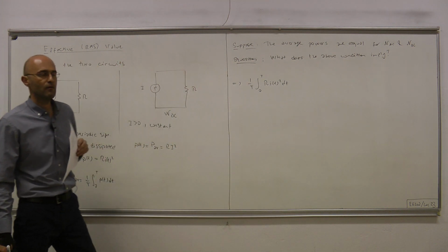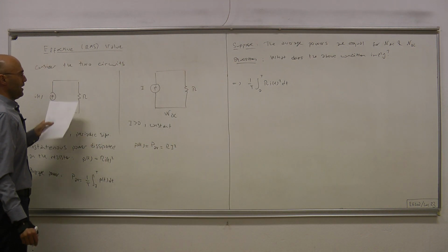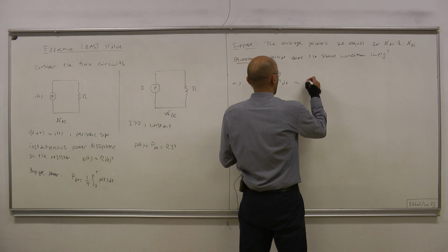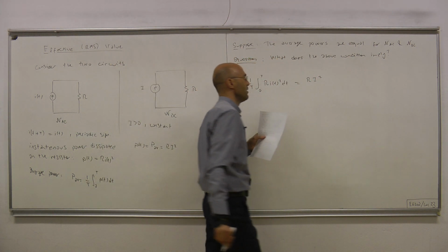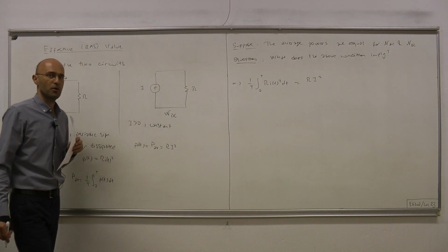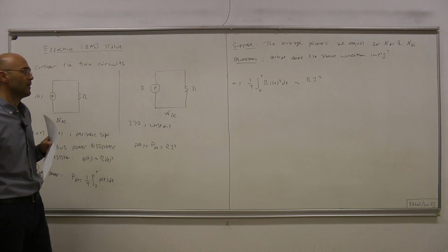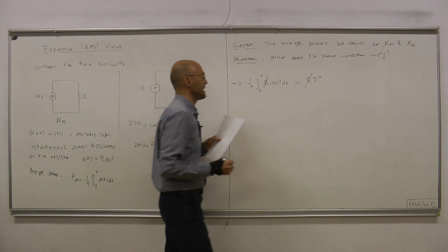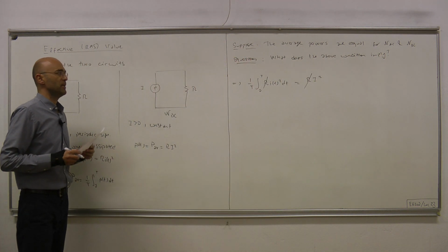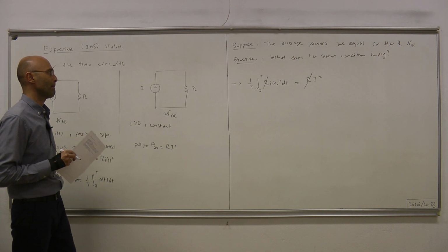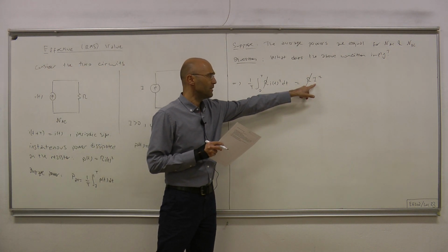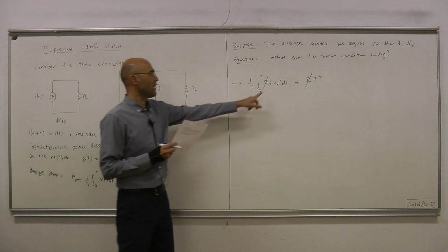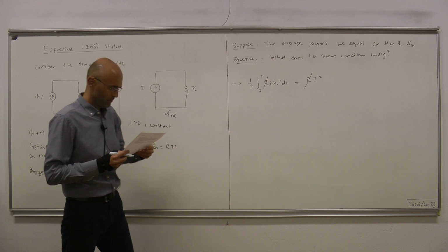That's the average power for the AC circuit, and we're told that this equals the power, both average and instantaneous, because the current source is constant, in the second circuit. Now these R's cancel, and immediately we obtain the relation between the constant current I and the time varying signal i(t).